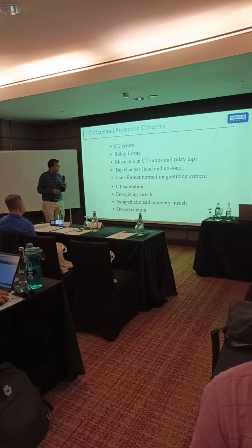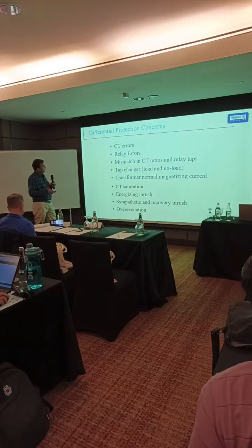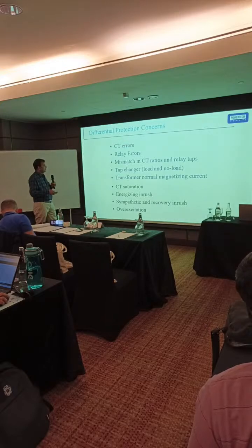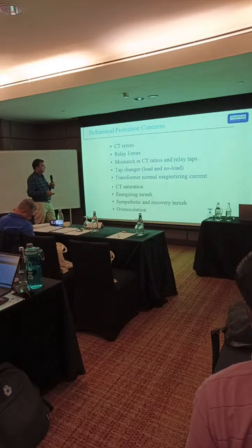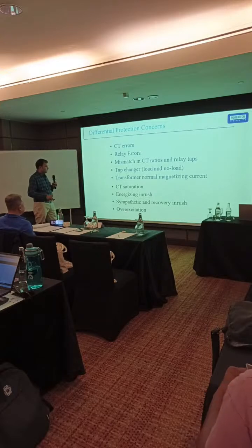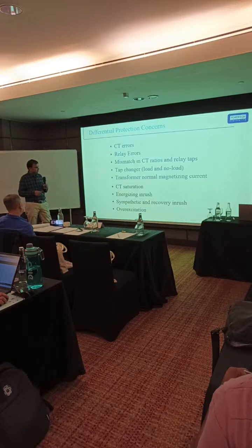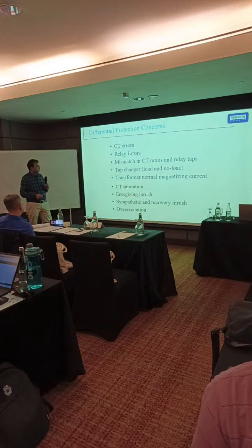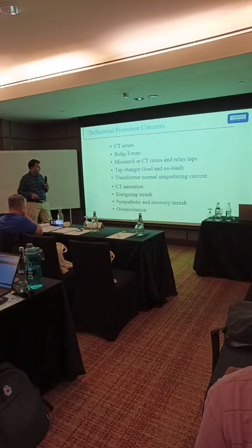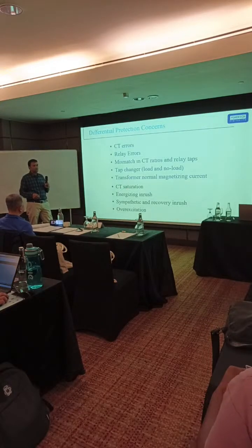These are the one part. This one is the other part. These factors create more difference in the relays. So that is why it is in two different colors. So CT saturation, energizing inrush, sympathetic and recovery inrush, over excitation. These are the factors which affect more.